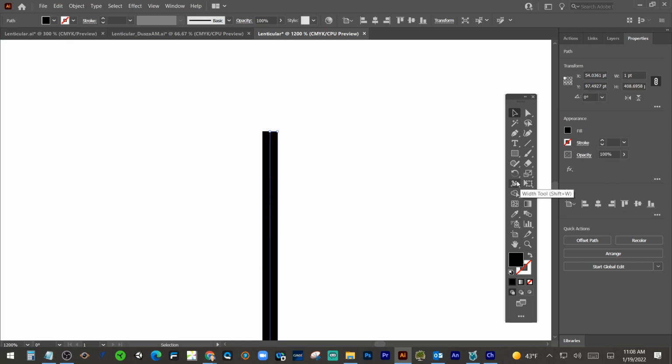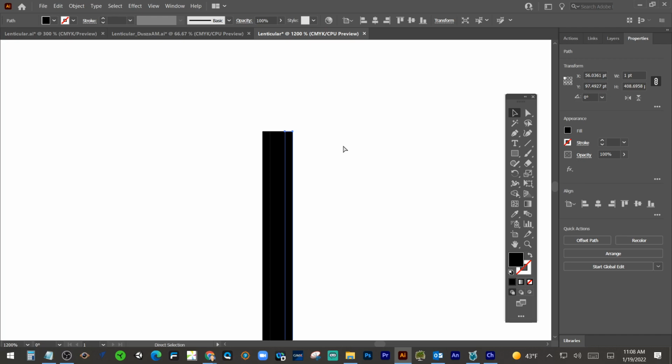All right. And then we could repeat that same process of moving it, because remember we talked when we started, we want that ratio of 6:1. But in Illustrator, to repeat the last command, you can press Control D. If I do Control D, it just made a copy of that. So now I have 3, 4, 5, 6.